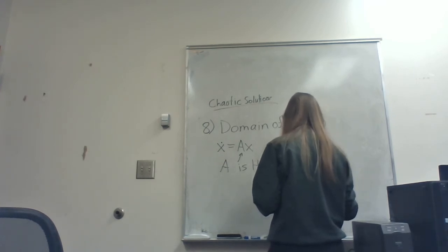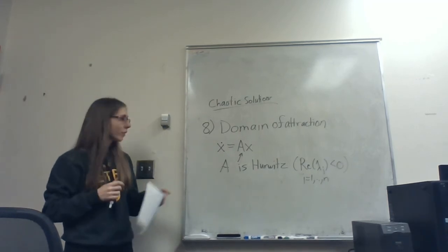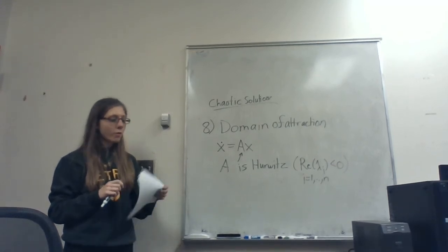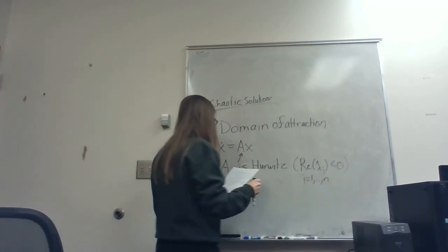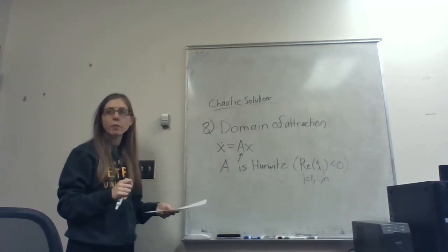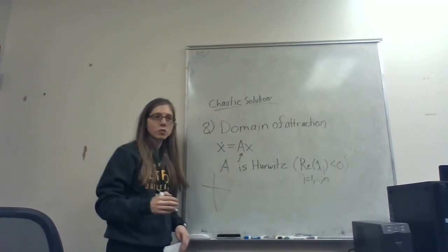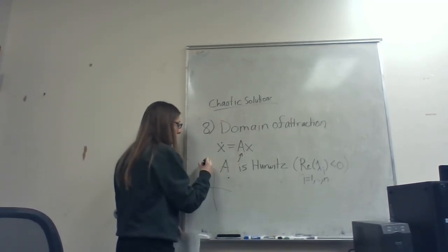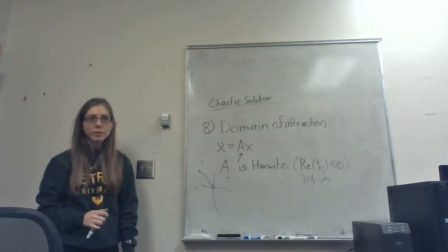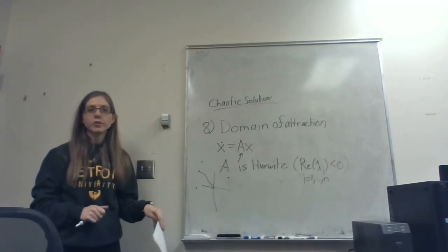for i equals 1 to n, so for all the eigenvalues. Every single eigenvalue is negative. What that means is, for a linear system, if it has negative eigenvalues, it would have negative poles. When you learn about something that has negative poles in undergrad control, assume there's no control here, that it's just pure open-loop dynamics. Starting from any initial condition anywhere in space, the closed loop state goes to the origin. That's what happens when you have negative eigenvalues or negative poles. So the domain of attraction is all of R^n.